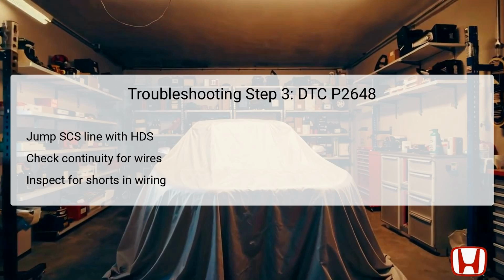With the connector appropriately disconnected, the technician then checks for continuity between the test points 1 and 2. This involves measuring between PCM connector C 51P, number 15, and body ground to ensure that there are no shorts.